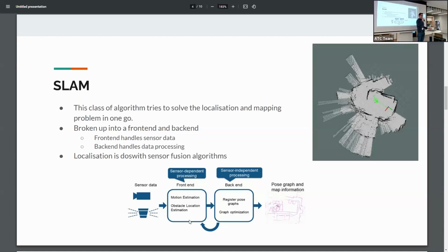And how we solve this is with sensor fusion. So we might say, we've got a little scan of our room. The distance between this scan and the previous scan was, let's say, 5 meters forward, but our wheels are saying we went 5 meters forward and 2 meters left, and we can kind of extrapolate to somewhere in the middle.